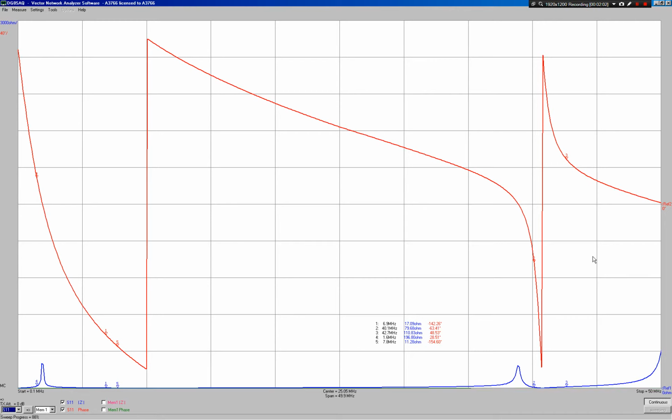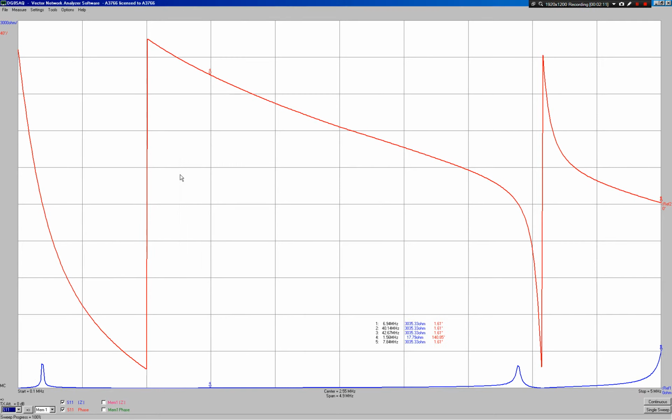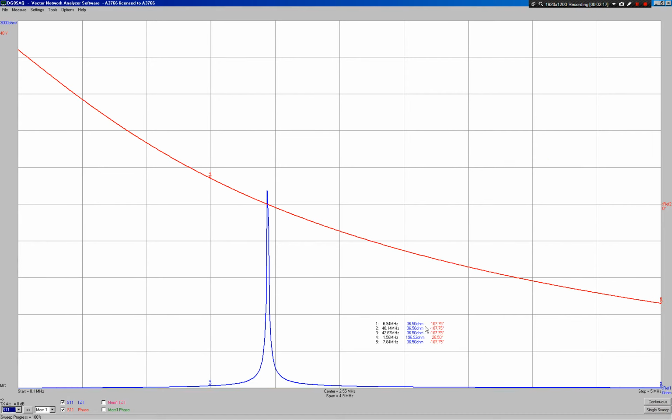And I'm now also going to reduce the bandwidth of the scan here. So I'm going to pause that for a minute. I'm going to go back into the 5 megahertz narrowband scan, and we've already got calibration for that. Do a single sweep. Okay, so there we just see the primary. We don't even see the phase change off the top here. Remember, that phase change was sitting up there somewhere around 7 to 8 megahertz. So now we just see that primary peak. I'm going to put it back in continuous. Okay, so it's just the primary on its own.